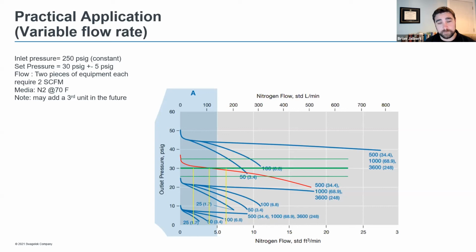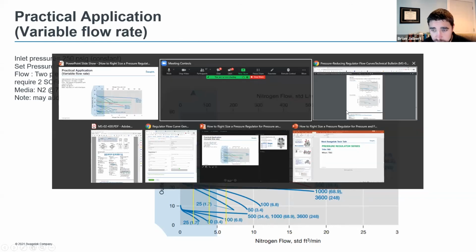Well, it'll have more lockup ultimately, but it might reduce where the area is. You might be better off with a higher sensitivity regulator, so a larger diaphragm regulator, or actually, if you don't have that much flow, go with a lower CV regulator. The lower your flow, the further you are from this lockup range. I'll show you a perfect example right here on the flow curves.